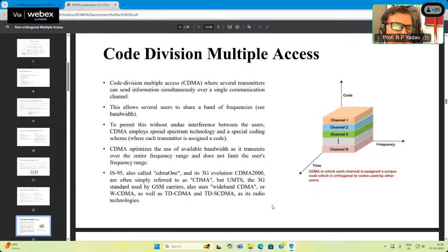That coding obviously is a very large code, Walsh code, normally the kind of block codes which have a bit length of near about 63 bits. So theoretically, 2 to the power 63 codes can be generated, looking at the bit length of the code, but it's very difficult. Particularly in communication applications, getting this kind of orthogonal codes becomes almost impossible.